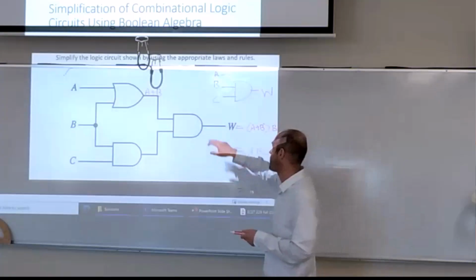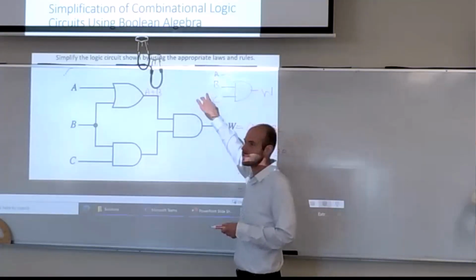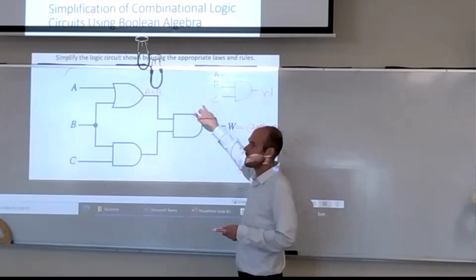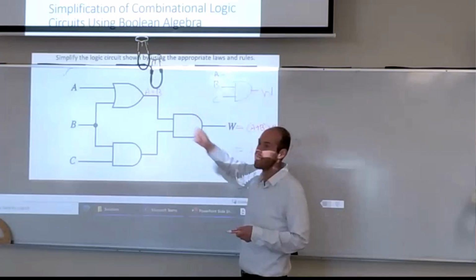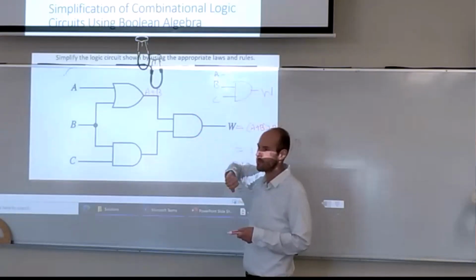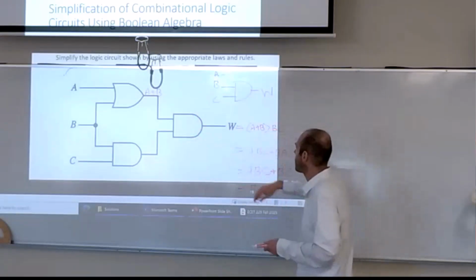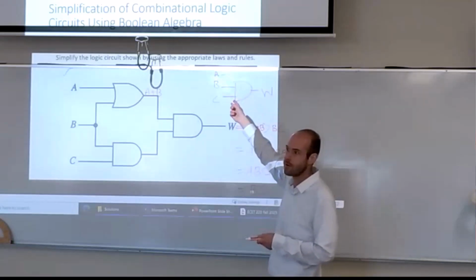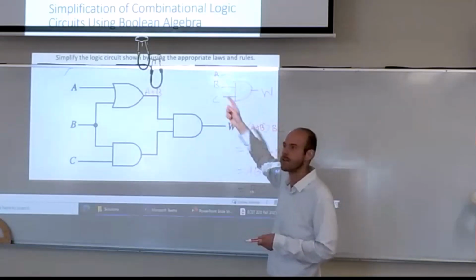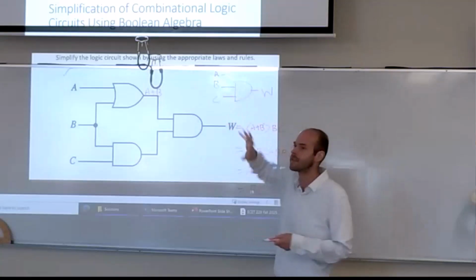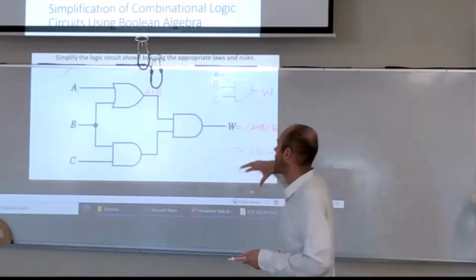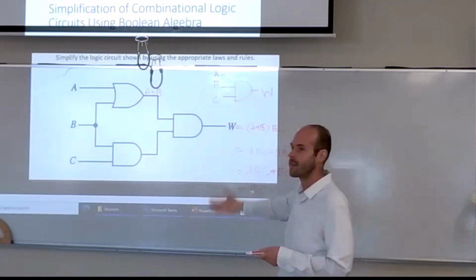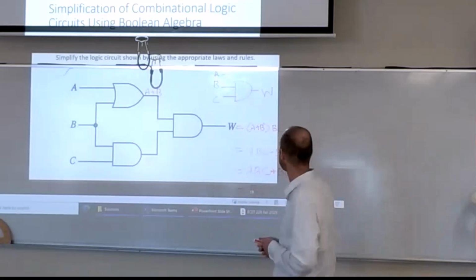So when you go to the truth table, you'd look for any combination of B and C. It would be the same if A was 0 or A was 1, meaning A is not impacting that output. So this can also reveal you added a $500 push button to your instrumentation panel that literally does nothing. So it is a design choice to help with your design, to find things that may not be necessary.